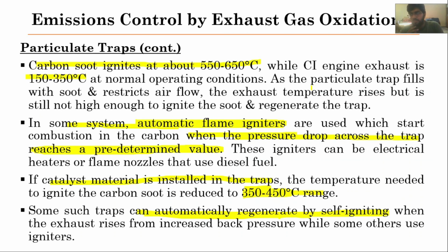So I guess this video has given you enough idea regarding how these particulate traps are operating, and it has also explained the normal or spontaneous regeneration. Then we might have some dynamic regeneration, and in the last, the service regeneration. And even after these regenerations, if there is a large pressure drop across this particulate trap, then we need to replace it. So this is how these emission control systems are operating.